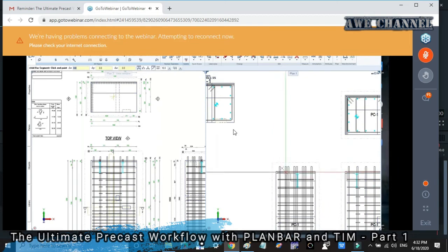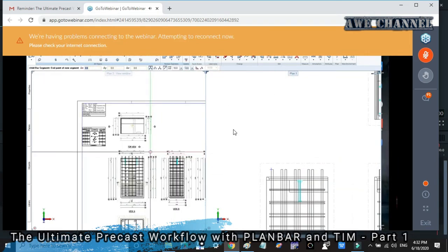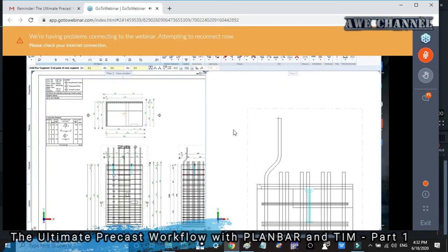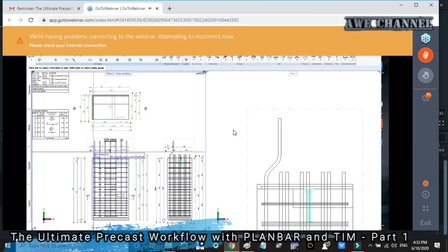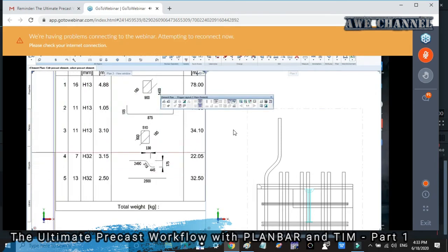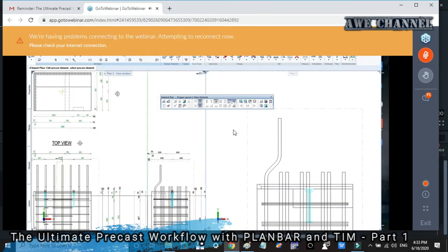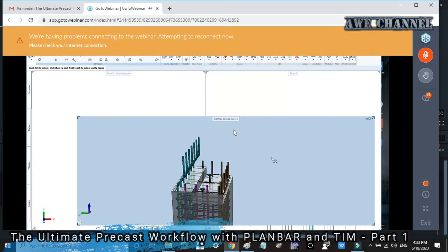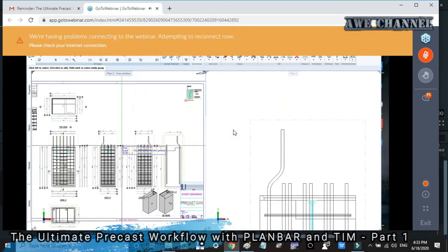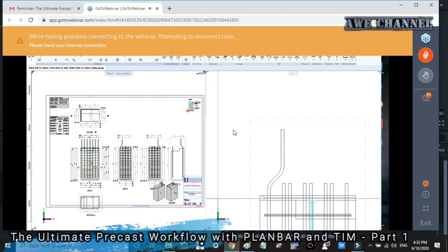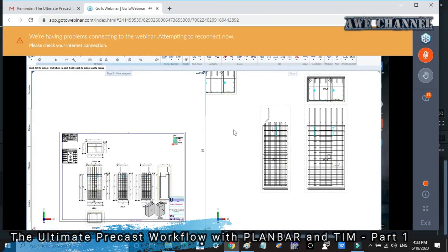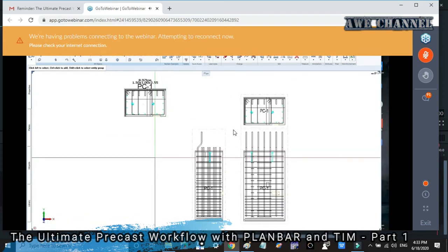Let's say you need to maybe crank a few. So even if I put the reference here, as you can see, my shop drawing also changed. Maybe I just refresh a little bit. And as you can see from here, I have added this bar, wherein you have these bars bended. And if I show you the 3D, how it looks like, it's something like this. So it's still possible to modify even after you have created the shop drawing, and it automatically updates, even if you're working from 2D to 3D or 3D to 2D. Okay, so that will be just a presentation for the structural precast elements.